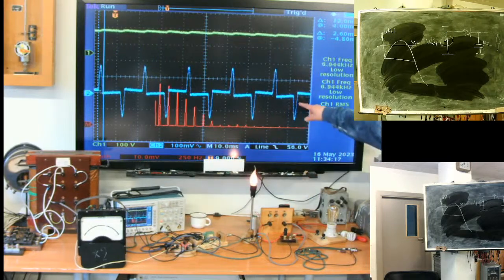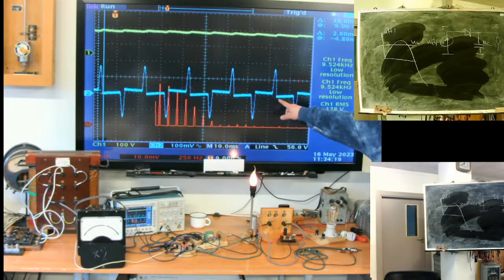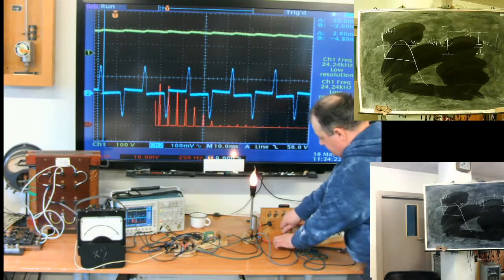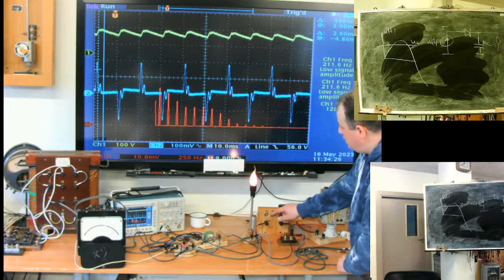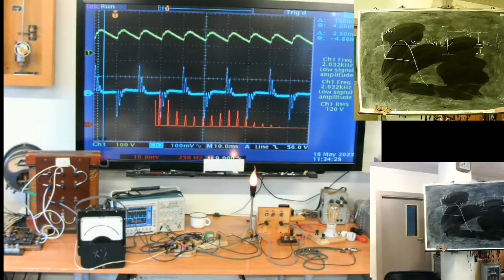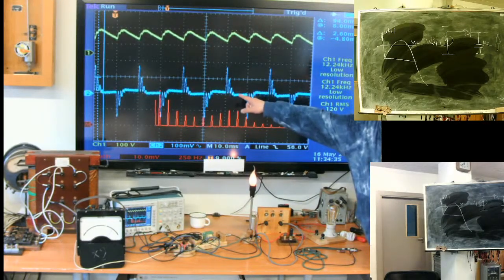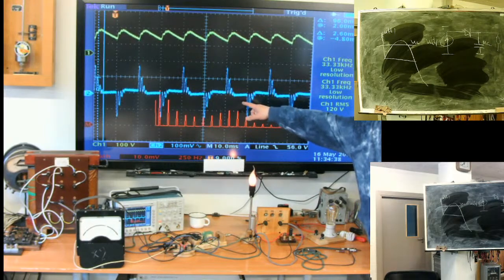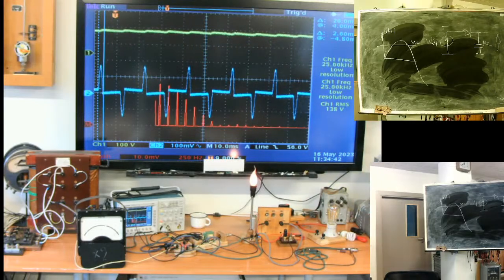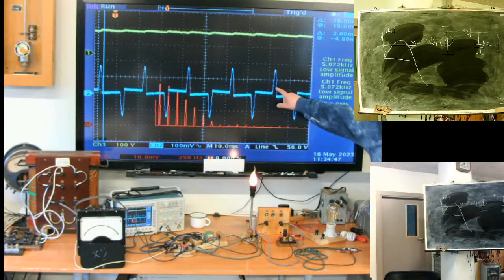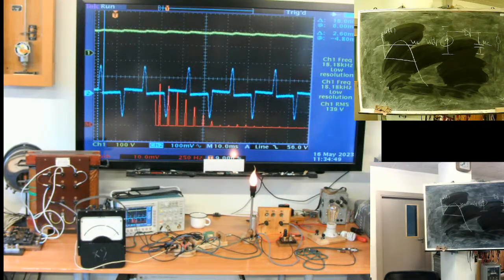Add a filter and you have a set of pulses. With an inadequate filter, too small or a dried-out capacitor, you see multiple peaks because the voltage is not ideally clean. When the filter is 200 microfarads, you will see a system of high peaks.